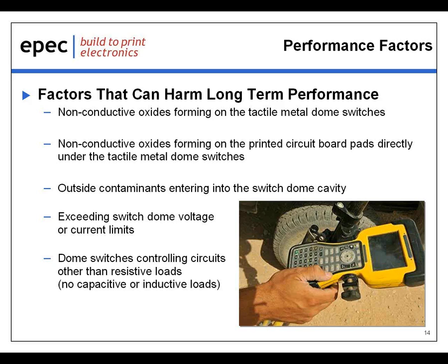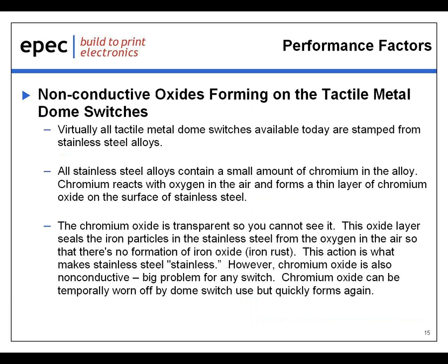Next is exceeding switch dome voltage and current limits. And finally, dome switches controlling circuits other than purely resistive loads, in other words, no capacitive or inductive loads. Let's examine these factors individually.